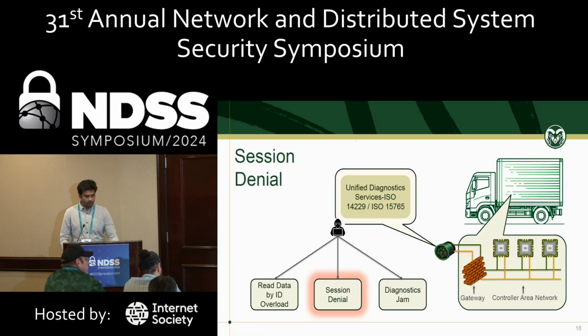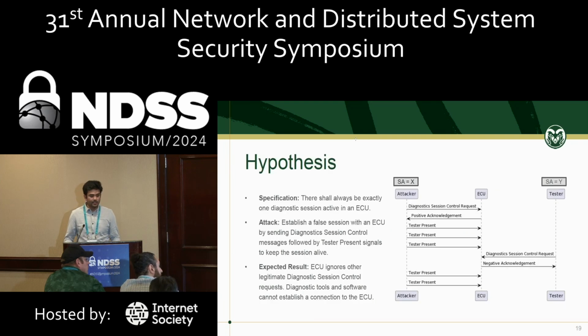Moving on to the next one, a session denial attack. It is typical for a diagnostic tester and the ECU to establish a diagnostic session when performing diagnostic activities. And the specification states, and this may be due to resource constraints in embedded systems, that there shall be exactly one diagnostic session active in an ECU.